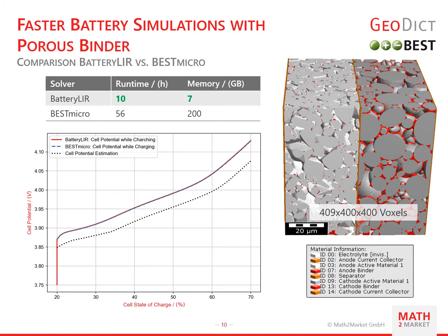With GeoDict 2022, it is now possible to simulate porous binder also with the BatteryDict solver. For the battery charging simulation shown on this slide, this leads to a runtime reduction of factor 6 and an immense memory reduction compared to simulations with the best solver. This means that one can compute much bigger and more realistic batteries with GeoDict 2022 than was possible before.